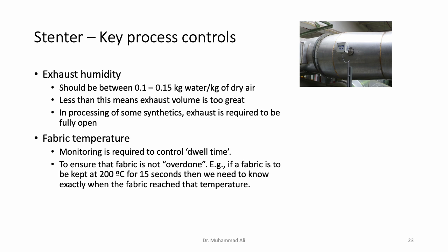The second key process control that we have listed down is the fabric temperature. Careful monitoring of fabric temperature is required to control the dwell time. Now, I've been using this term for a while because I'm assuming that you are well aware of the heat setting process. Probably you have studied heat setting in detail in your textile dyeing course. However, if it is not the case, then you can let me know, and I will prepare a short video regarding heat setting as well.